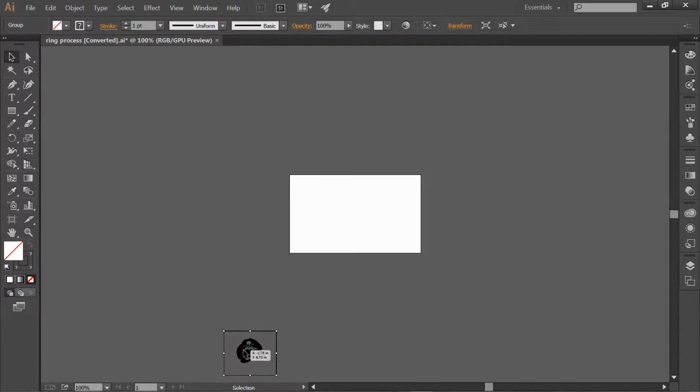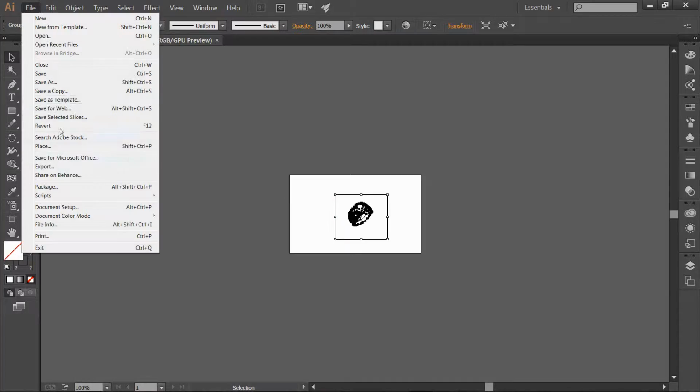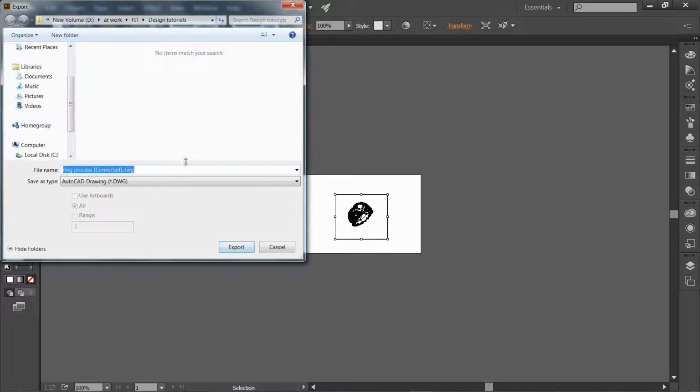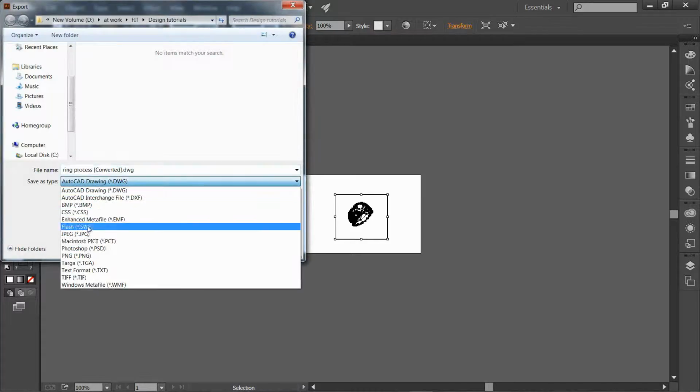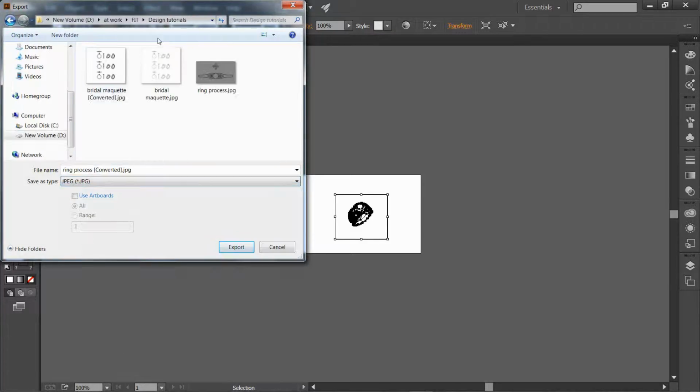Click anywhere on the image, pull it in, change the stroke weight to 0.33, enter. Leave that selected and export it. I want it to go out as a JPEG to the same location, and that is fine. I don't want it to be confused with my background bitmap,